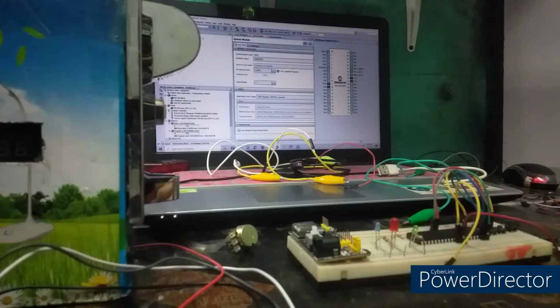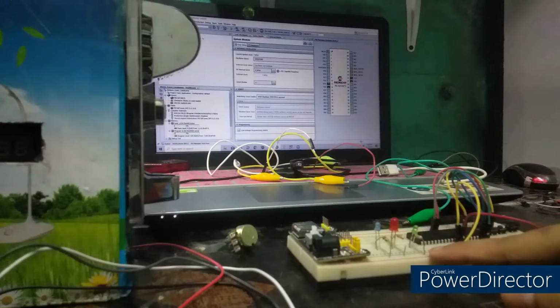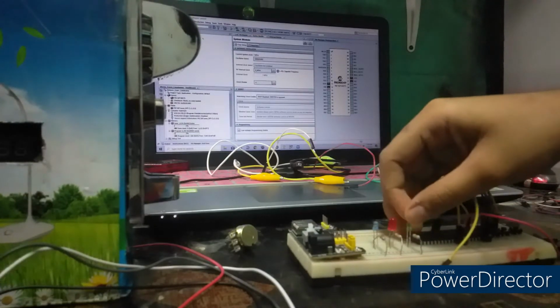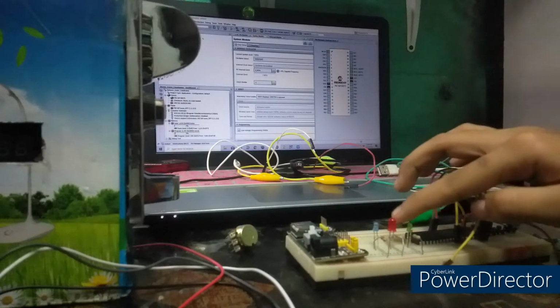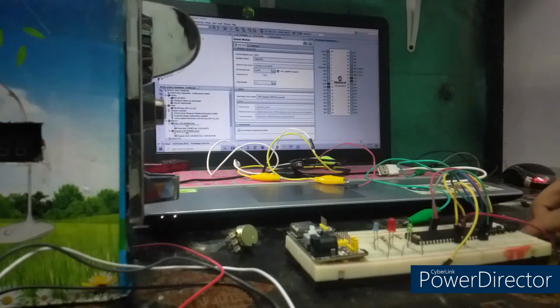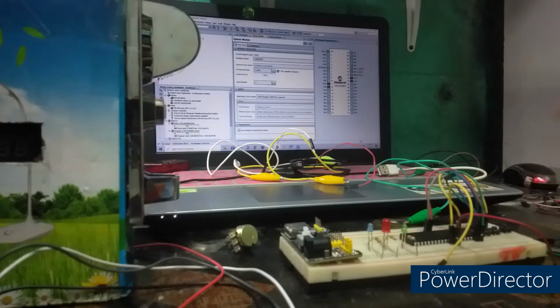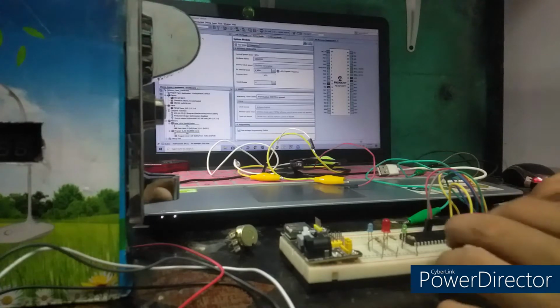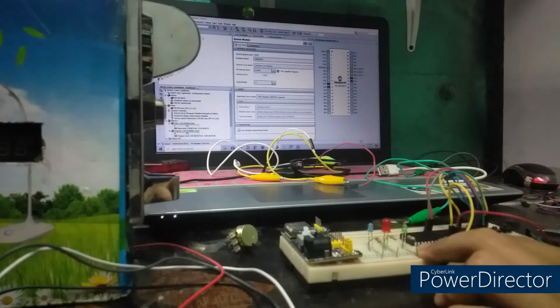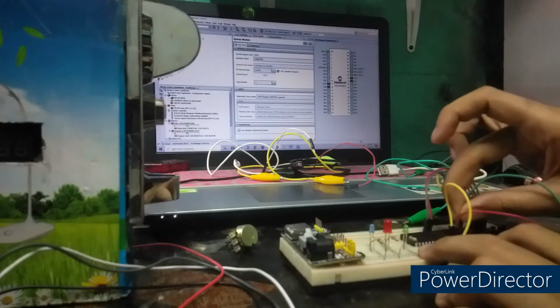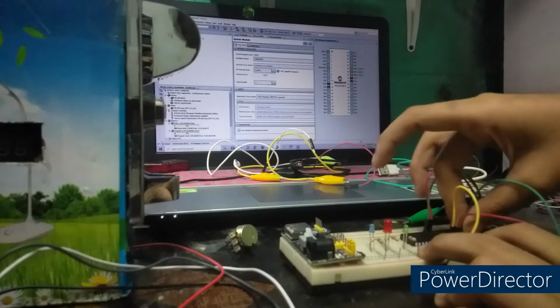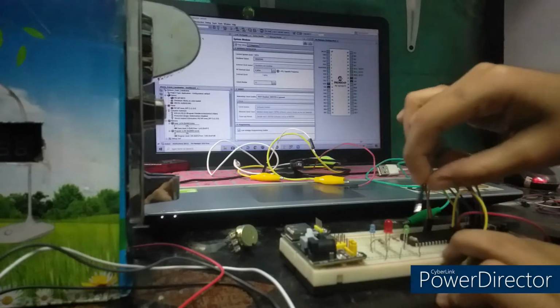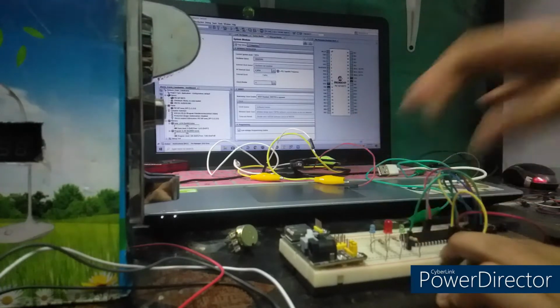So now, starting to construct our circuit, we already set up our 3 LEDs here. Namely, the green LED will be for our 1 peso indicator, red will be for 5 peso, and blue for our 10 peso. Our green LED, our L1, is connected to our RB0, which is on the 33rd pin of our IC. RB0 is up above VDD, so this red wire here. Since it is green, we will be connecting a green wire here, then connect it to the positive terminal of our green LED.